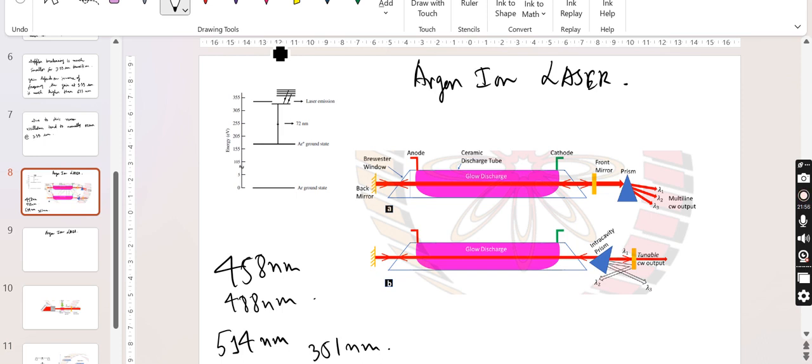The basic construction features are similar to the low pressure gas discharge laser, except that here a solenoidal spiral is around the discharge tube in all but low power argon ion lasers. The electromagnetic coil put across the plasma tube generates a strong magnetic field longitudinally along this axis. This purple colored thing is the magnetic field, and it has been generated by the electromagnetic coil.